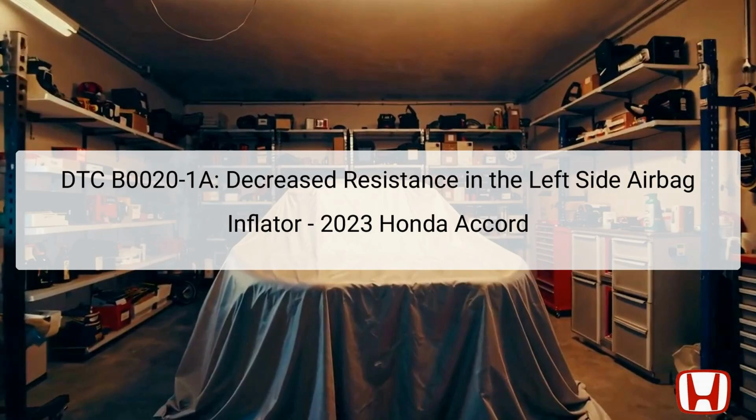The error can signify potential issues with the driver's side airbag, the external wiring circuitry, or the SRS unit itself. Understanding the nature of this specific DTC is vital, as it directly impacts the vehicle's safety features, including airbag deployment functionality during a collision. A comprehensive approach is essential for accurate diagnosis, necessitating thorough inspection of all associated components and wiring before concluding on the fault.